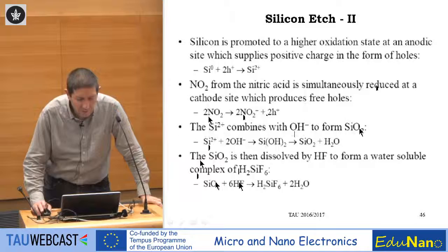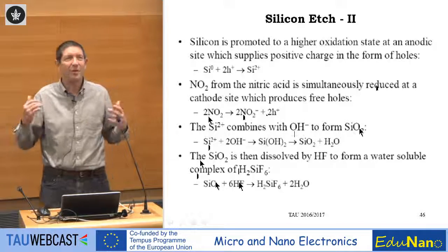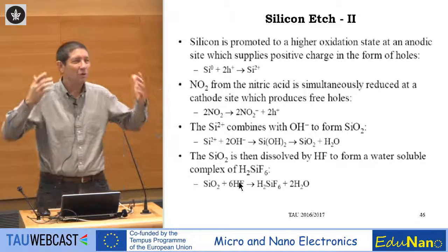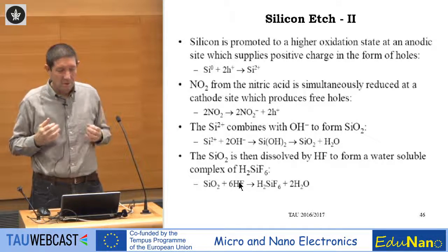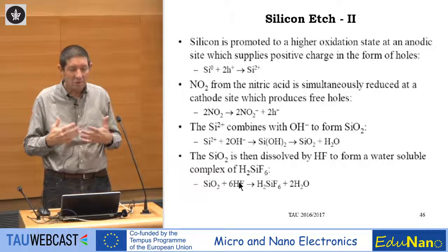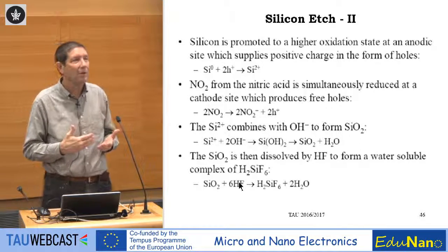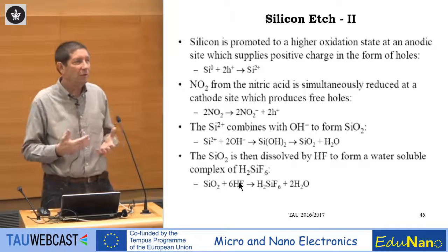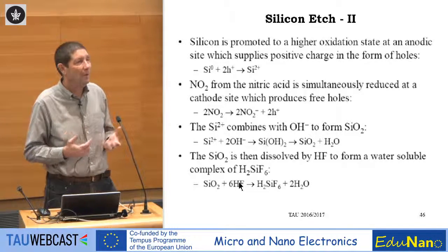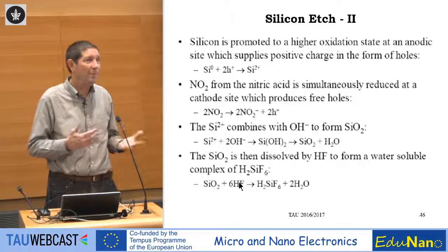So previously I gave you only 2 reactions, now I gave you 4 reactions, but still the total number of reactions is more complicated. Why am I showing you these steps? We see that the actual chemical process involves electrons and holes in the semiconductor. This explains, by the way, why the oxidation rate can be a function of doping.